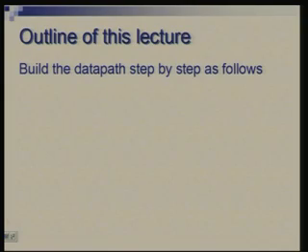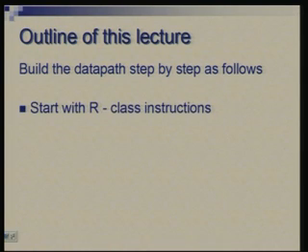So, we will build this design in small steps, so that you can see each and every step clearly and get a clear picture of how the circuit is getting designed. So, we will start with a small set of instructions. First, we will take only R class instruction, which includes arithmetic, logical and comparison: add, subtract, and, or, and SLT. So, that will be only part of the solution. Then we will add instruction by instruction and see how the whole thing can be built.